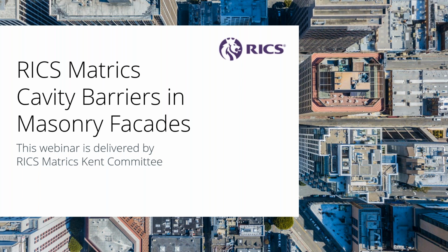In terms of the product itself, if it does get wet, we do have some ad hoc data in terms of it being completely submerged. But the product itself, being stone wool, is non-hygroscopic, so it doesn't absorb water like a sponge. It naturally repels it. So it will always naturally dry out itself, bearing in mind that if it is saturated, it will become a bit heavier. As long as the foil faces haven't been torn off while it's wet and being handled, if it's in situ and gets wet, it will just dry out naturally. There's no problem, you don't need to change it out or anything.